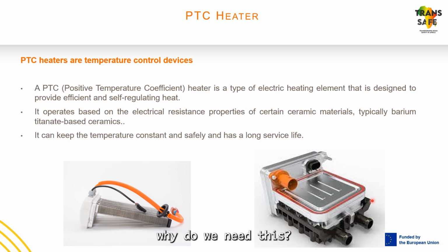So, the question is, why do we need these PTC heaters? Well, the first characteristic of an electric vehicle is that we don't have a source of heat. In combustion engines, the engine is gonna provide us that heat. But here we don't have an engine, so we need to use this electric resistance to heat the air or the coolant. Okay.